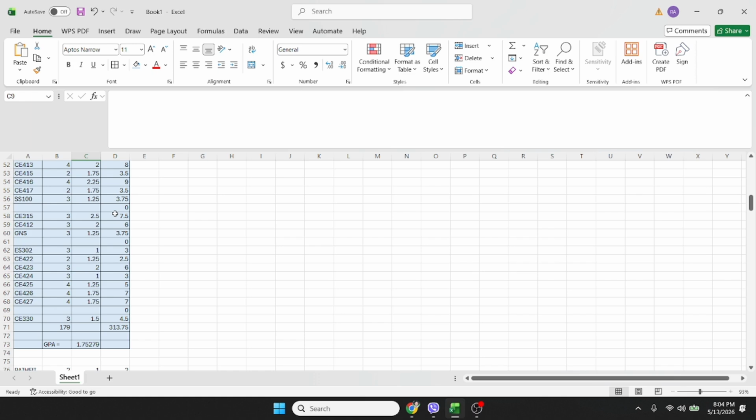So, the support reaction in the direction of applied shear introduces compression into the end region of the beam. Loads are applied at or near the top surface of the beam and no concentrated load occurs between the face of support and critical section.